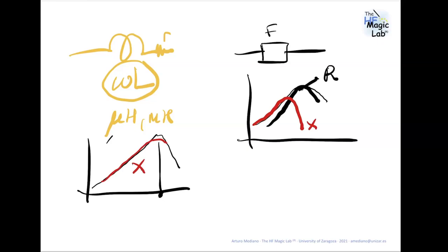So when we select a ferrite for EMI purposes, usually we are interested in selecting a frequency, the frequency where we have the problem, to introduce losses. So the EMI, let's say, disappears, is converted to heat. But when we are using inductors for filtering, the noise doesn't disappear. The noise is reflected to the source. Perhaps it can cause some problems or not. So it depends on the application. Okay.